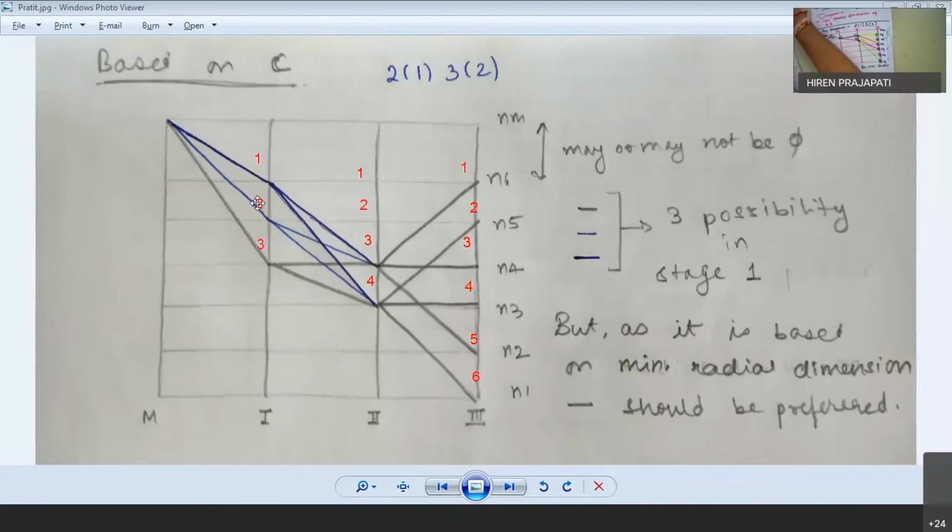If I do the total, obviously I'll get a higher node number. So here 6 plus 4 plus 3, so we get 13 as the node number. So the higher the node number, the worse the diagram is as per the minimum shaft diameter criteria. This is the basic theory of node number, and you can apply it quickly on your ray diagrams to select the best ray diagram.